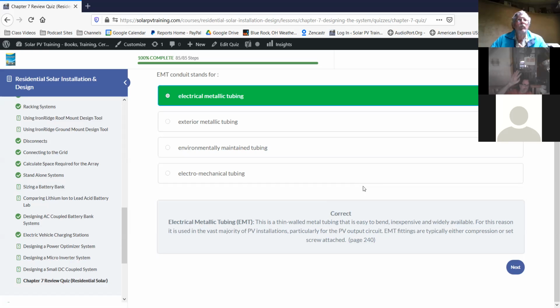Yeah, John. Well, the other thing too is I doubt that they're worried about some kind of magnetic field, because when they said MC cable was allowed, they didn't specifically say it had to be steel. You can get MC in either steel casing or aluminum casing. The aluminum casing doesn't suck up the magnetic flux, whereas the steel would.